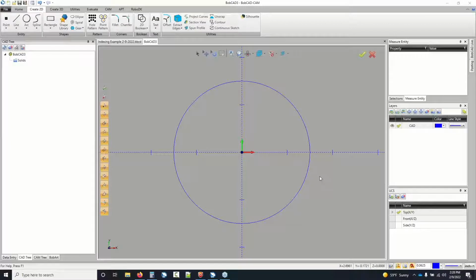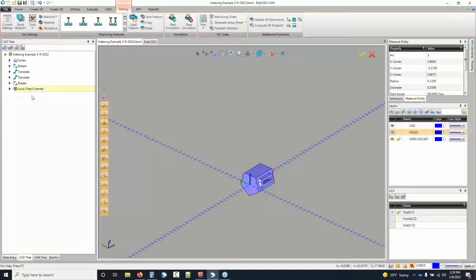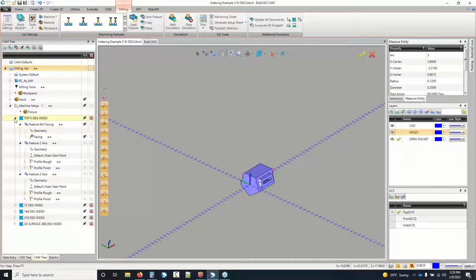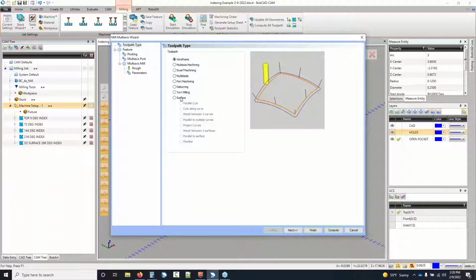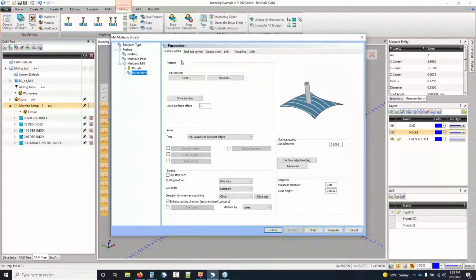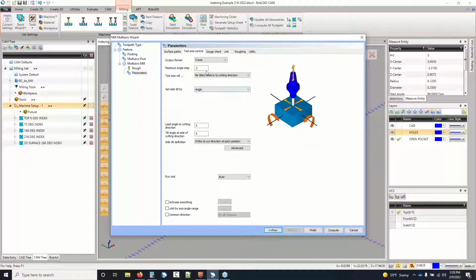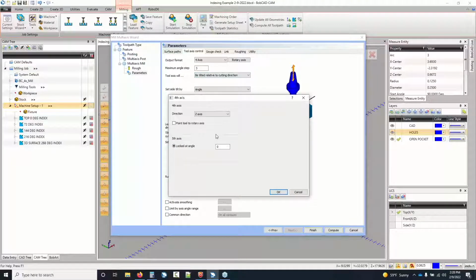One second. So Mark said maybe I'm remembering some angle control in the premium 4-axis toolpath. Yeah, there might be. There's definitely more options. Give me one sec. We'll go back to the wrapping. There's definitely more options when you get into the 4-axis pro toolpaths. Like these ones. I could go with 4-axis, and then there's things in here, limit by angle ranges. I mean, really, that's about it.